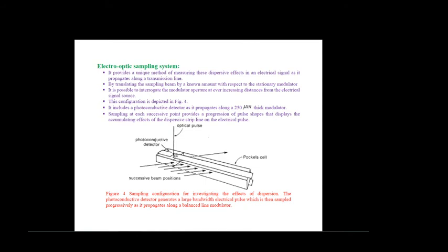So the higher frequencies are traveling at a very slow speed. Thus, as the pulse propagates, its higher frequency components appear later in the waveform. Figure 5 illustrates the effect of dispersion produced on a picosecond electric pulse at different points along a 250 micrometer thick balanced microstrip transmission line. Now we compare the dispersive characteristic study.